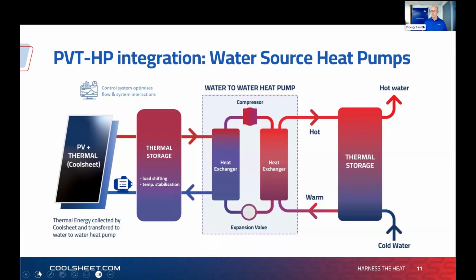We strongly recommend a buffer tank, just so that you've got a stable input into the inlet side of the heat pump, and it's not searching and being inefficient in its energy use. Yeah, and also because we're storing that at lower temperatures, we're actually capturing a lot more thermal energy at a lower temperature. And then you step it up with the heat pump, up to what you'll be telling us, above 200 degrees now is possible.